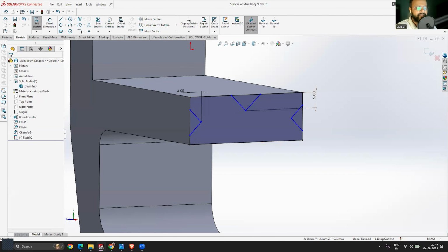This 15. So now this sketch is fully defined. Now I will simply click on finish sketch. Then we'll select that profile, and this time I don't want to add body onto this object. We want to make a slot cut of this triangular pattern. So if we go into the feature panel, instead of using the extrude, we'll use this new tool that is extrude cut, right? So this tool is especially to make a cut of any profile onto your existing body.